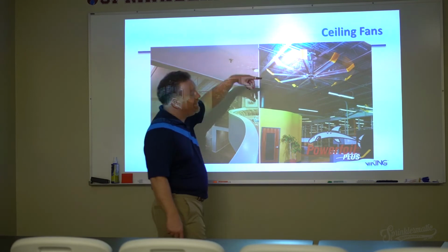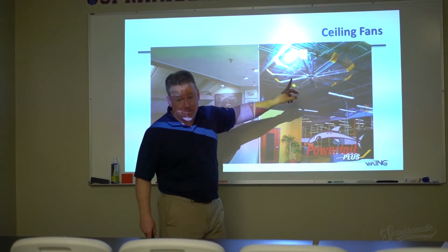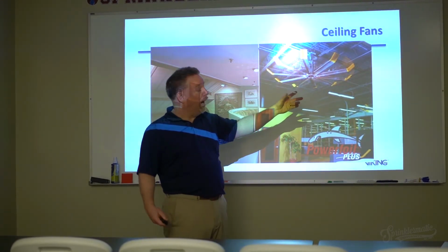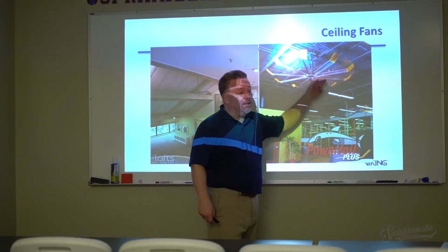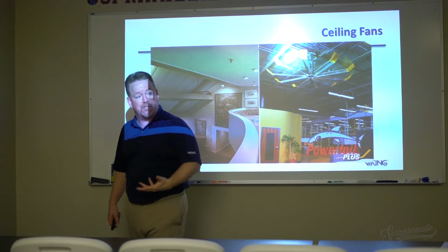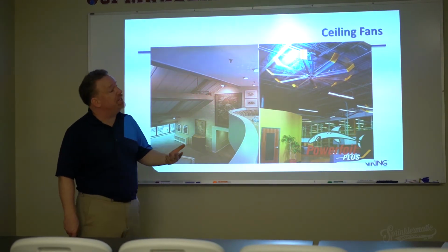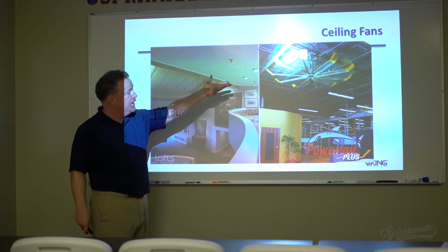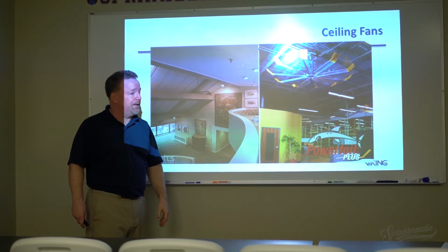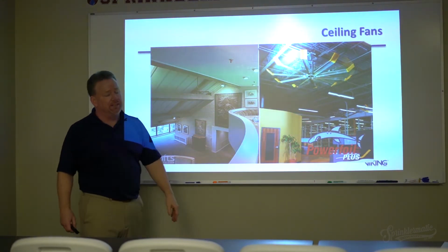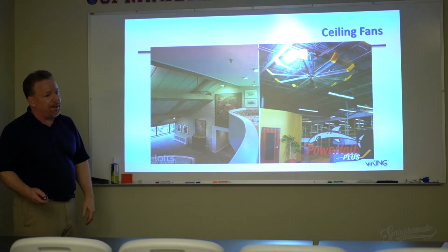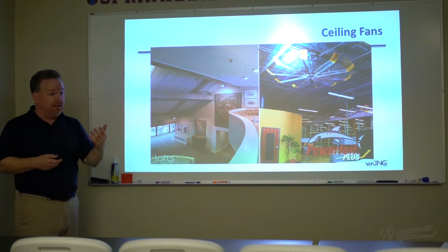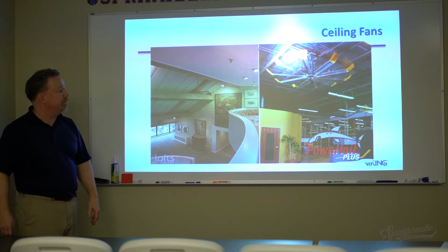The problem is, what does this thing do when it comes to my sprinklers? We didn't know at the time. What we thought was that it could be an obstruction to the spray pattern, especially for ESFR sprinklers. What we found out is that, no, not so much. They didn't have the impact that we thought they were going to have on either ESFRs or on the standard sprinklers.